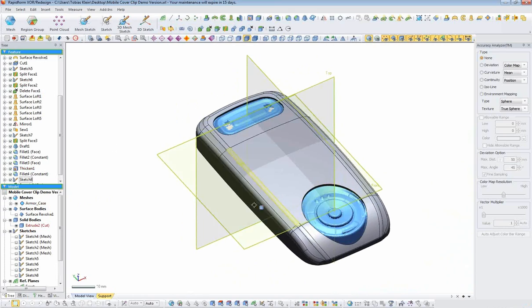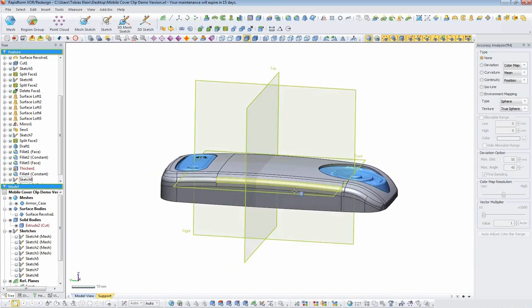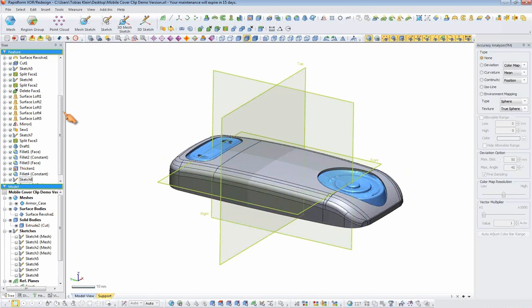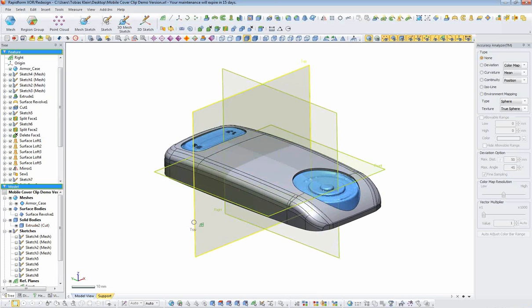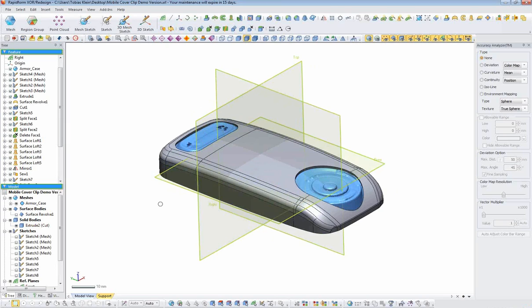I think you pretty much got the impression of how to operate this tool to get the features out of your original part and to get a construction CAD model. But now, how to do printing. To go to printing we need a mesh again, we need STL again. To get that STL we just create an empty STL mesh.